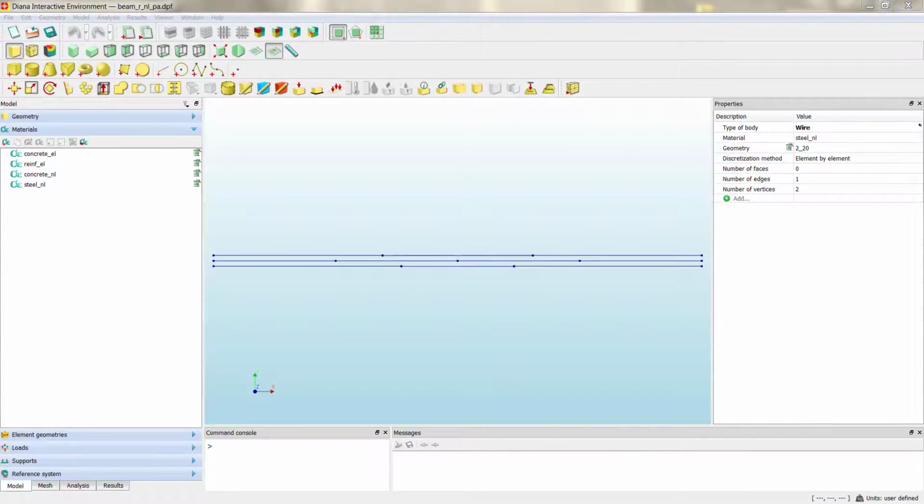As we might expect cracking on our beam, we should consider the possibility to increase the integration points of the cross-section. Each beam element has 2 integration points, and each integration point is defined by different cross-sectional integration points. So we should increase the cross-sectional integration points to have better discretization of all the cross-section in the plane of the cross-section.